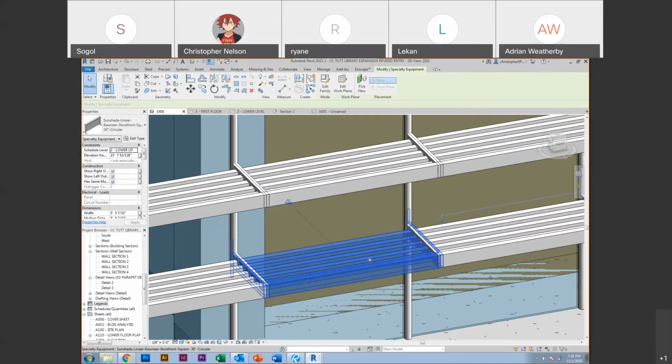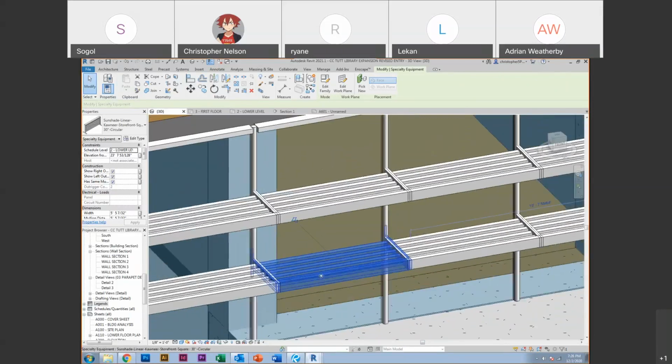But the reason I say just download it is that this one has the option where you can tell it the width and distance to the mullions, which is important because each time you have a project with different mullion lengths, the supports are going to come out of the mullions. This way you can tell it to span mullion to mullion without having to adjust it every single time you have a different condition.